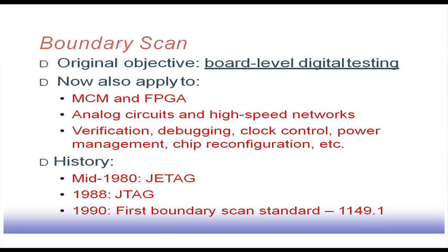Basically it becomes a tool to send commands to various chips. Say a chip has different power modes, and if you want to change the power mode of the chip, you can send a command via this boundary scan. There may be an interpreter or analyzer available at the chip input, which will look at the command coming from the boundary scan, and accordingly reconfigure the chip to go into a low power mode.